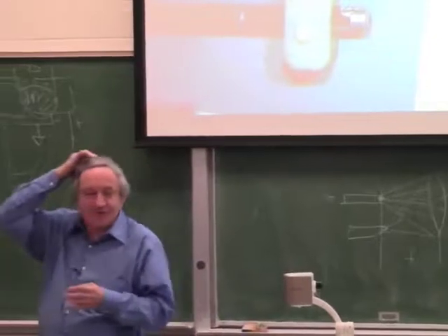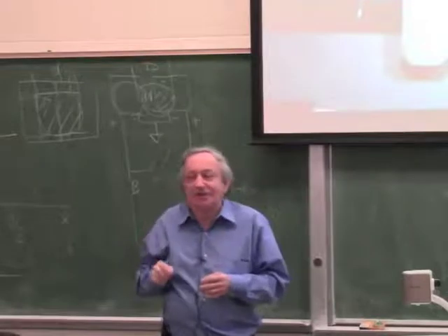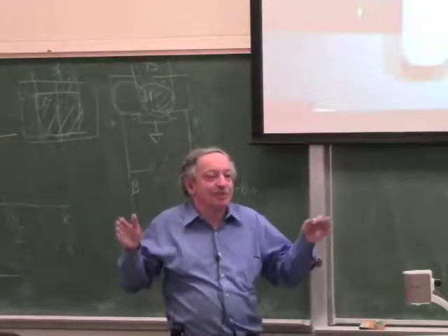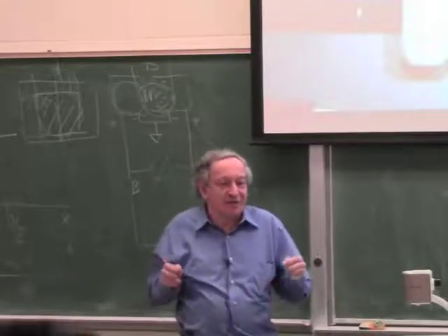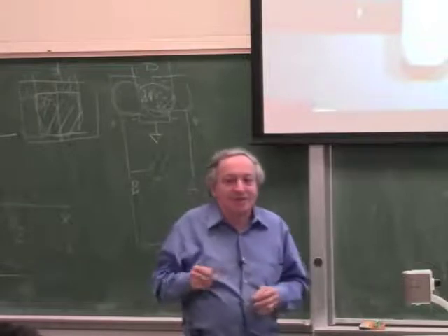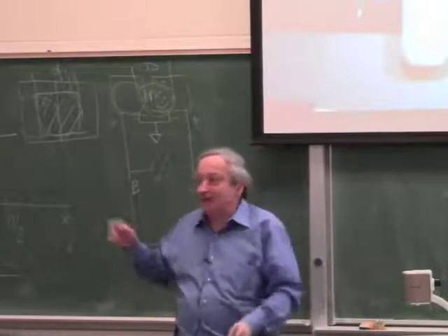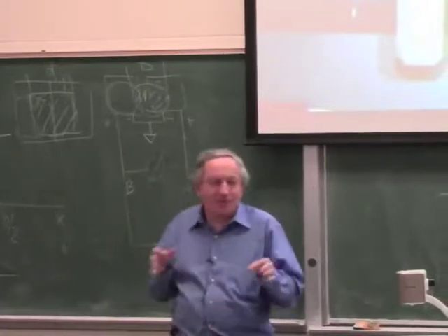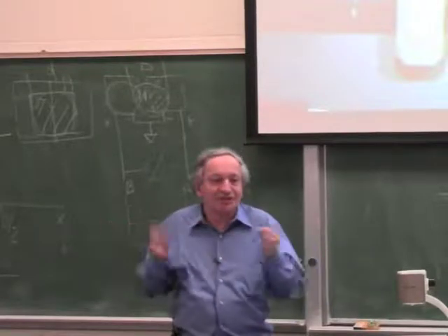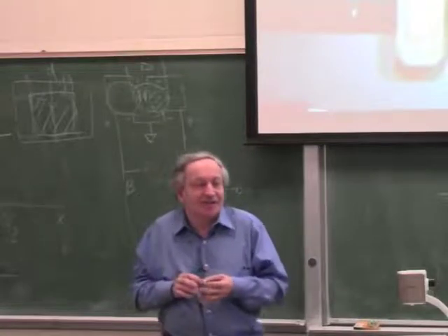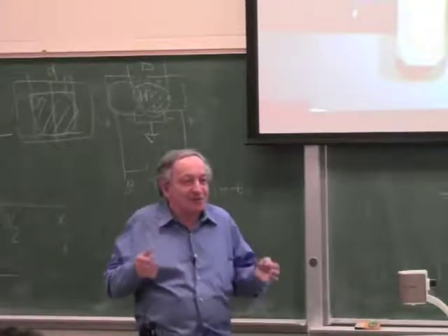Like in an LVDT, I couldn't do that. In the LVDT, if I wanted to measure a small distance, I had to make a small LVDT. If I wanted to measure a big distance, I had to make a big LVDT. You can argue, you can say in mechanical system, you can make a lever. So if you wanted to measure 1 meter, you can make a reduction lever. But it's very complicated because the lever goes at an arc and the lever has mass, it has backlash, it complicates life. But if you do an optical sensor and you put a lens in front of it, you can image the scene to any size you want. The light has no mass, well, it has a little bit, but you don't notice it. It has no delay, right?